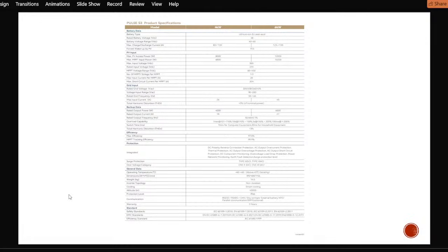Now as we know, 1 MPPT, 2 strings, up to 28 amps maximum PV current, and down to the grid, you can see 220 to 230. The voltage range, as I already said, from 90 to 280, regulates it properly without any force. Then we're talking about the total harmonic distortion. Now, the excellent range for this is around 0 to 3%. When you see an inverter that can give you that range, you know this is excellent. You are getting clean energy from it, less noise, less distortion, right?